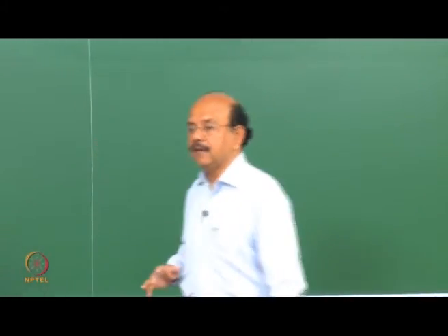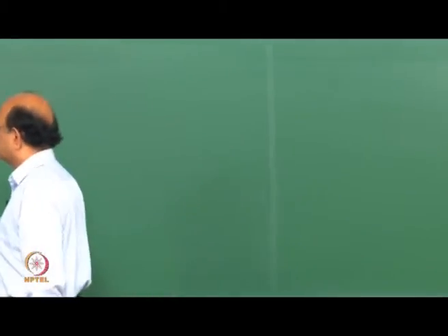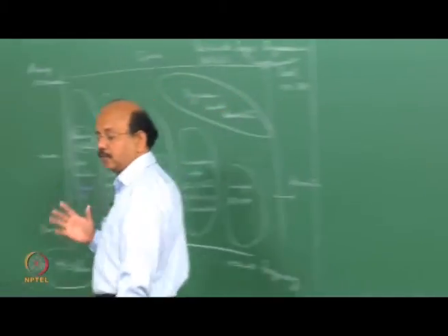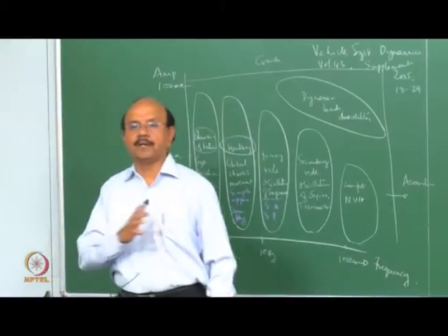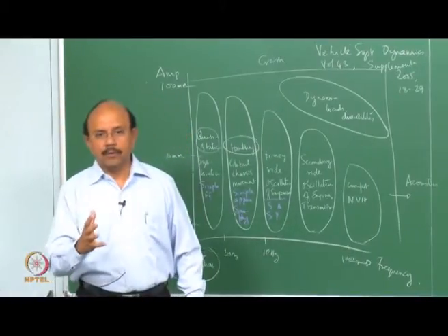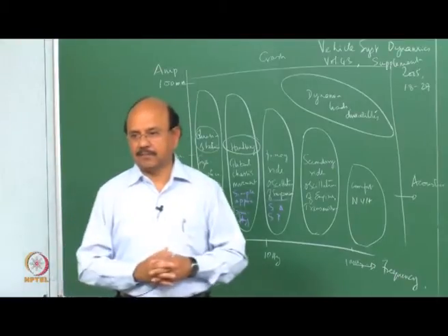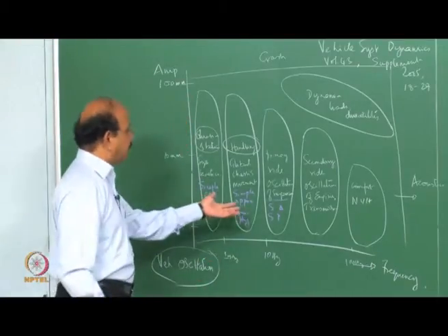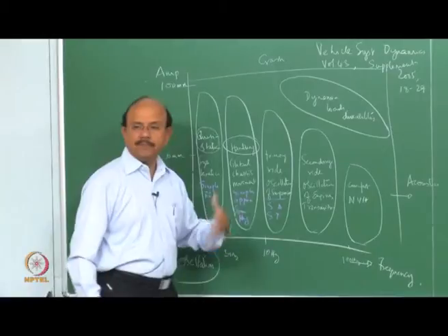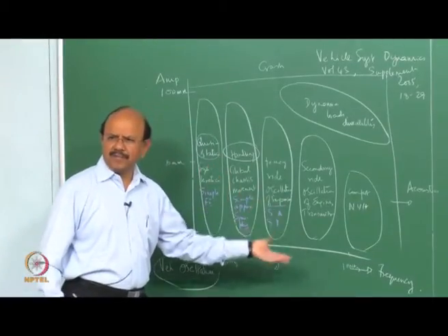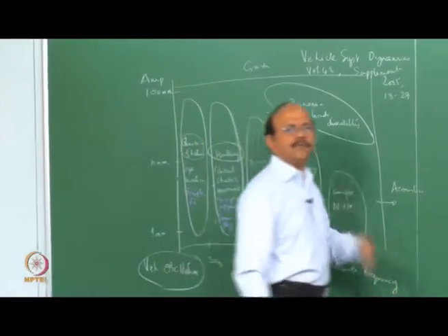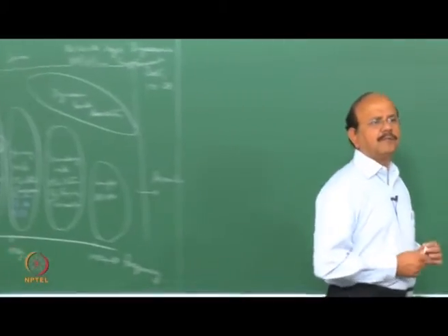But ride is a topic which is not only affected by, note this carefully, the road. Today ride encompasses much larger things. For example, there can be oscillations of the engine, transmission, and so on, which may be at a much higher frequency, maybe about 30 hertz.